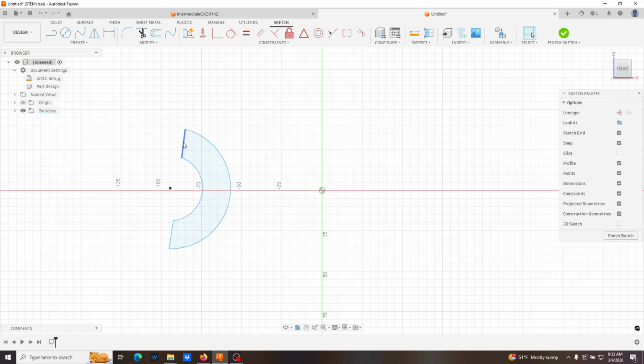So then to finish this off, I'm going to select this line and add a vertical constraint here. And then, again, there are multiple ways I could do this. I could use guidelines, I could use reference geometry, but I'm just going to click this line and click this here, and then make these coincident. Now you'll see when I made it coincident, how it angles to keep it in line with that. So it's again how these can add to each other.